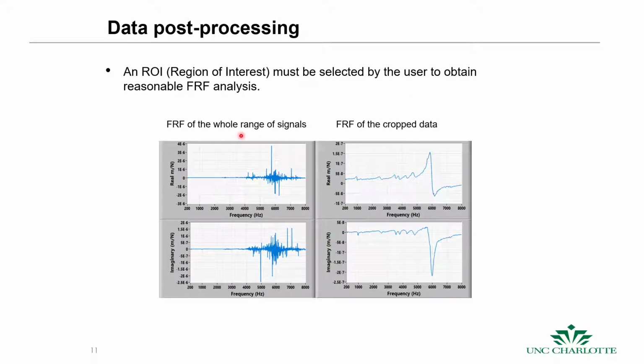We can decompose the signals with the area of interest, and we get something like this in the real and imaginary. And as we saw, each one of these peaks can be related to a frequency that's present in the system, a natural frequency of the system. For continuous structures, we actually have an awful lot of frequencies, and you see here at this frequency, we have a lot more energy. That means that the response is much higher to that input force, which means this frequency is a lot more sensitive to being excited, and something that we should pay attention to.